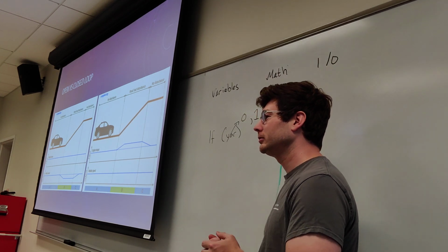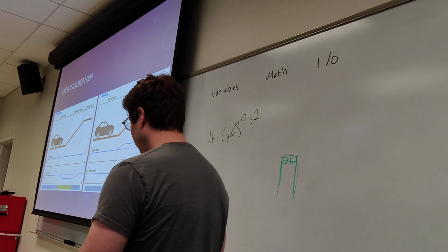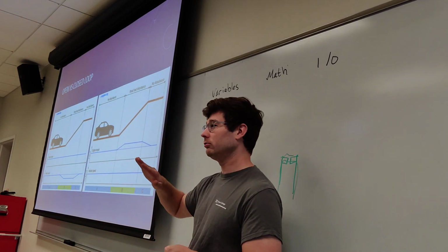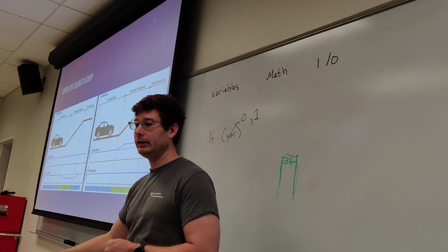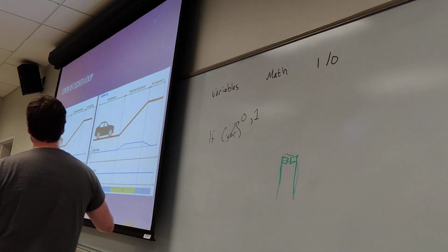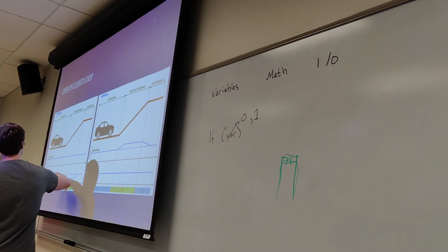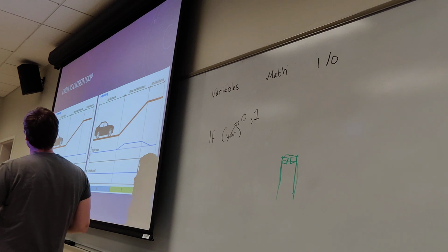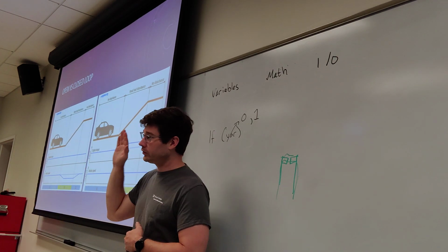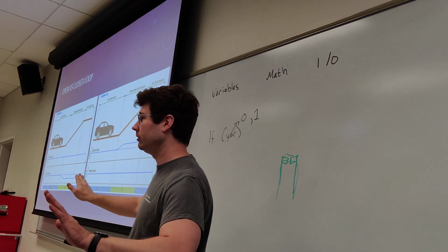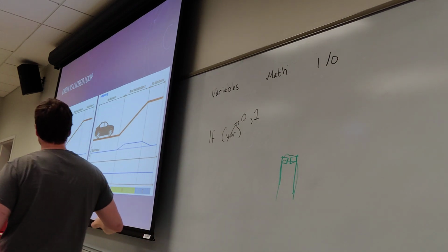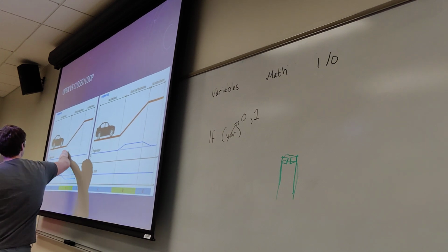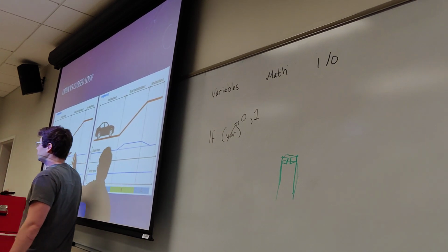It's not as involved. You can essentially run something at the speed that you think it needs to run at, and it will kind of just go, right? If it goes faster than that or slower than that, you won't be able to tell because you don't have a sensor to counteract that speed. So in our car example here, where we have a car running in open loop, that means that someone's pressing on the accelerator and that's it, right? They're not responding to any changes. They're just hitting the gas, and then the speed takes a hit because the environment changes, and our input is not changing accordingly.